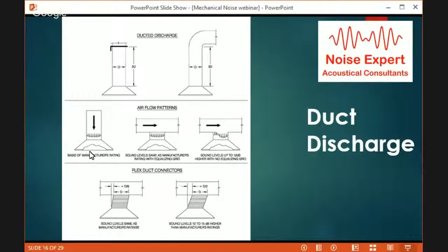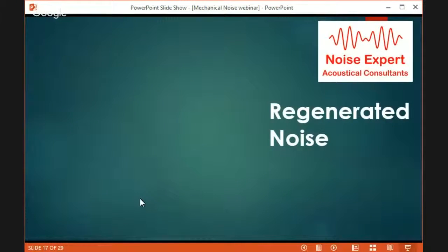Yeah, this is the basis of the testing, which isn't always what you see in the field, but that's how we select diffusers. We add up the criteria in the room. If it's an RC 35 and you have 5 diffusers, each diffuser has to be below that so that the sum, depending on how far they're spread out, will stay below that 35. And so you select them, and maybe they're at RC 30. That might not happen if it's not that smooth, the flow over that.